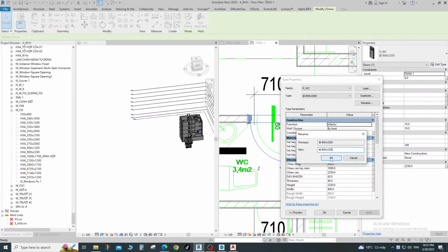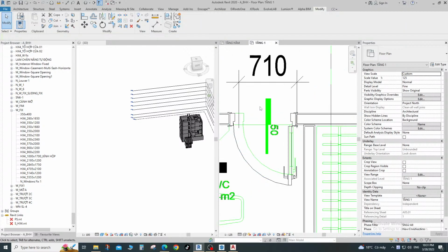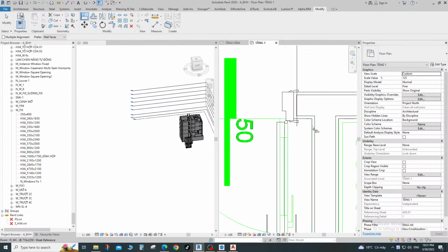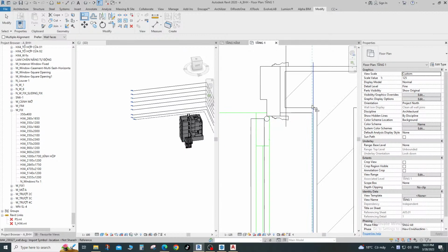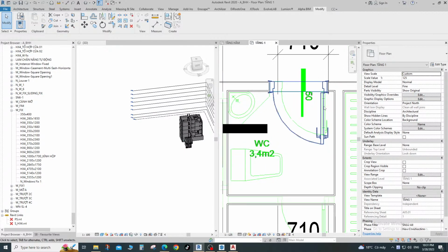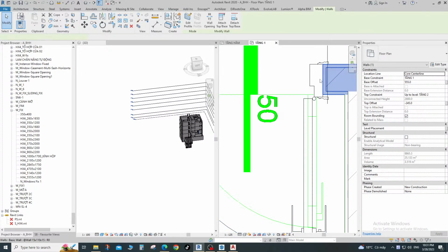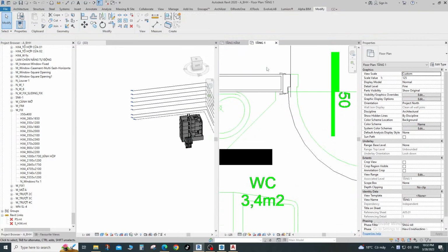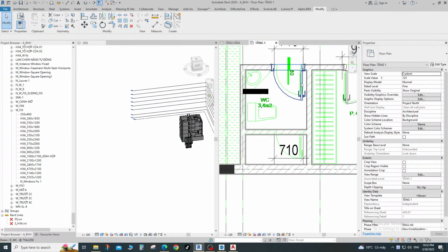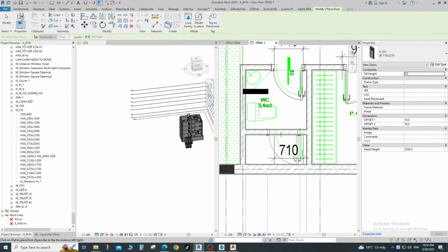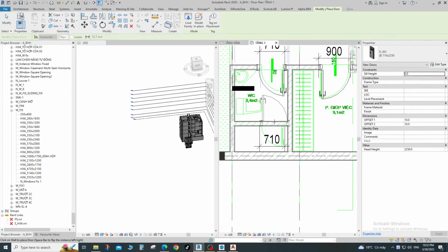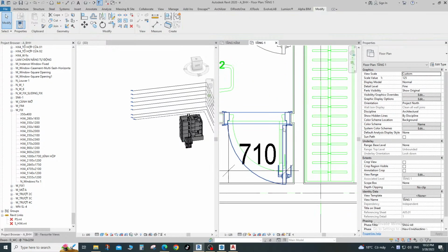It's quite easy to place because you have all the floors. What you can do is use beam, and for example, I'll just pick this one, and you can use the pick line. With that 3D snapping, you can just pick the edge of the floor, so you can place under that. Okay, so let's do it again. Pick line with 3D snapping. You can just place. Oops, sorry. Control Z. Place them directly under the floor. Okay, so that's it. Yeah, I think that's it.